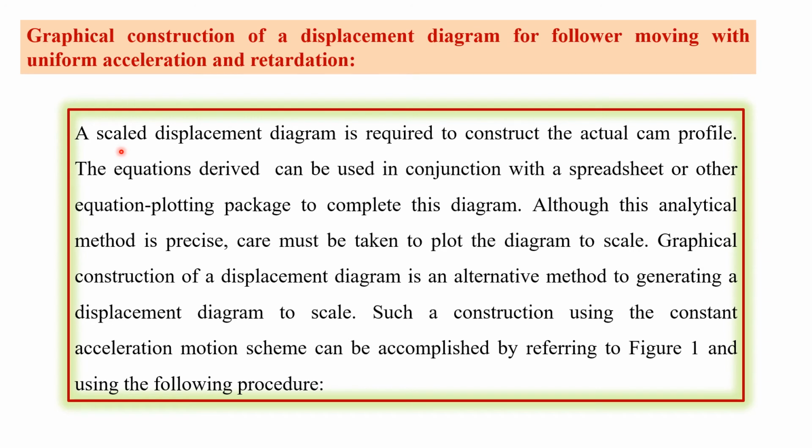A scaled displacement diagram is required to construct the actual cam profile. The equations derived can be used in conjunction with a spreadsheet or other equation plotting package to complete this diagram. Although this analytical method is precise, care must be taken to plot the diagram to scale. Graphical construction of a displacement diagram is an alternative method to generating a displacement diagram to scale.